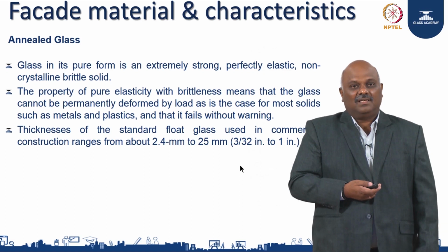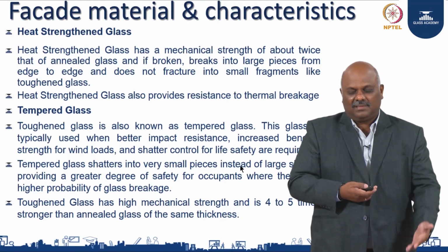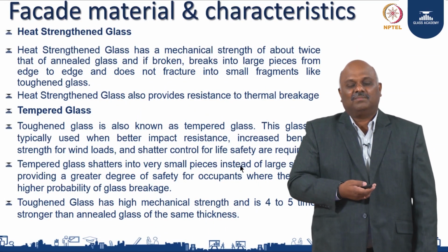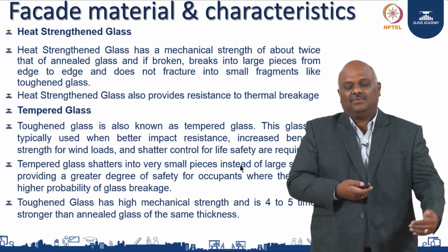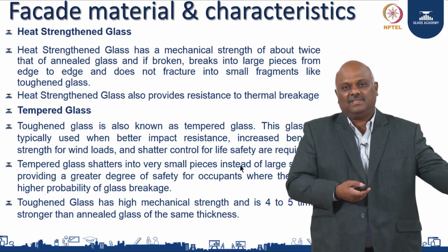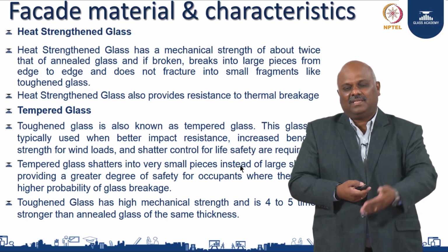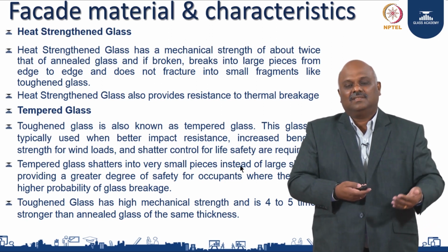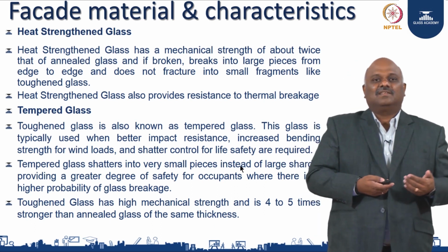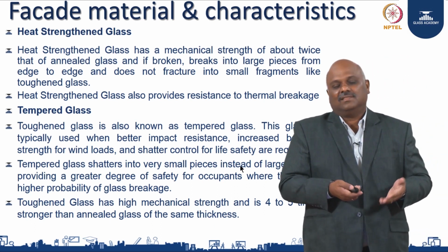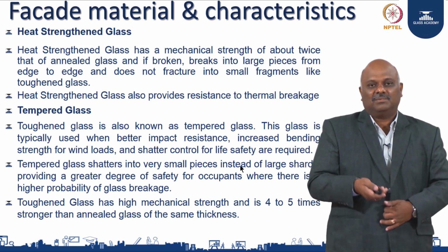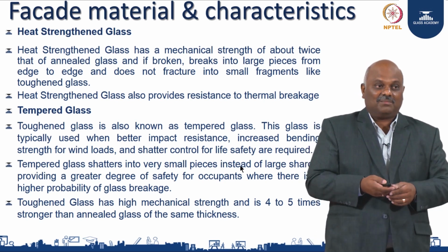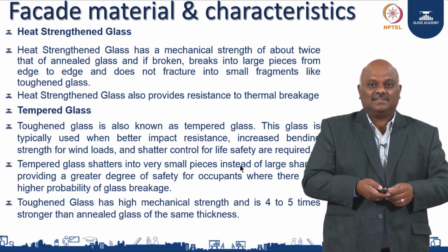Depends on your requirement. Either you heat strengthen your glass, depending on the requirement by the structural engineer, or you temper the glass. These are all ways to harden it, like when we see aluminum T3, T4, T5, T6, it depends on the building requirement and what you are designing for. Glass is also the same, whether I want a heat strengthened glass, a tempered glass or a float glass, it depends on the structural requirement by the engineers.